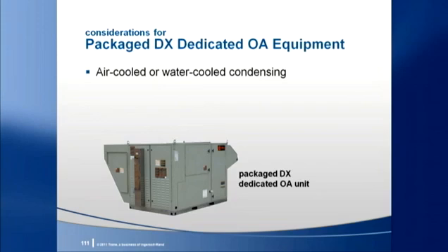If there is no water loop, then an air-cooled condensing unit or similar is the likely choice. Another consideration is that reheat may be necessary at times. It seems obvious that air forcibly cooled shouldn't be reheated any further than necessary to prevent overcooling of the space.